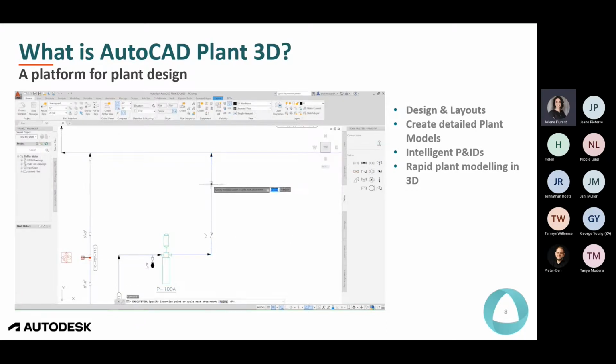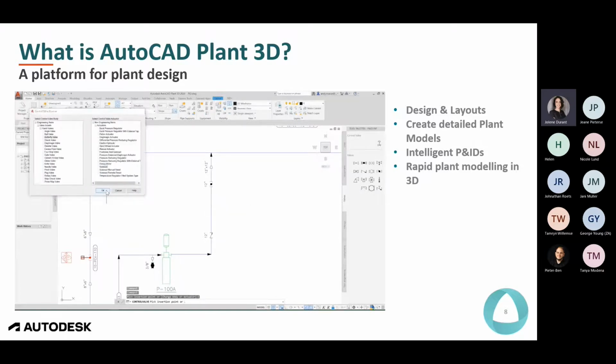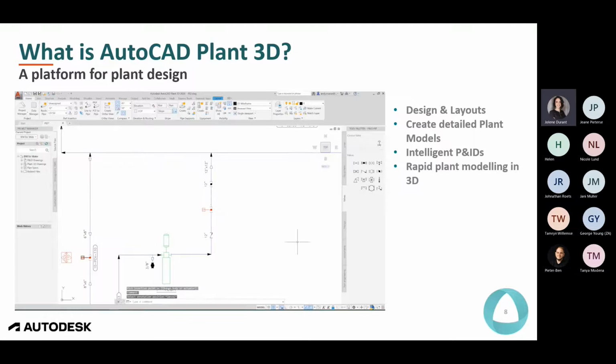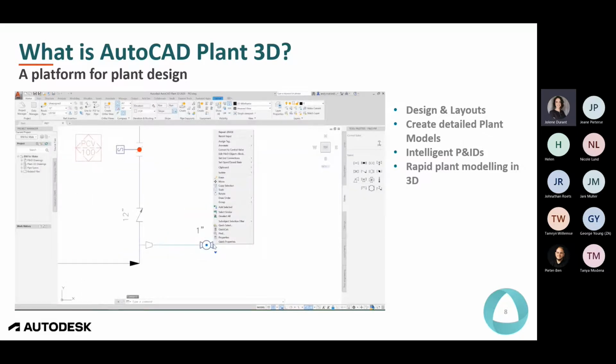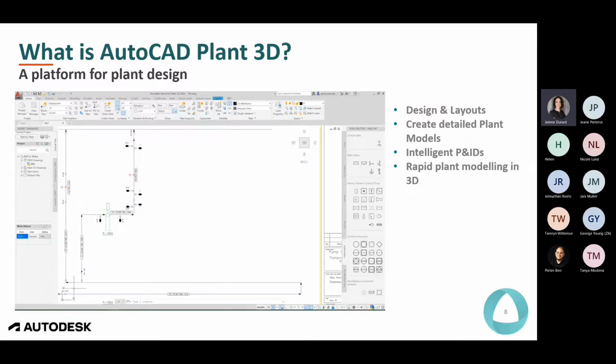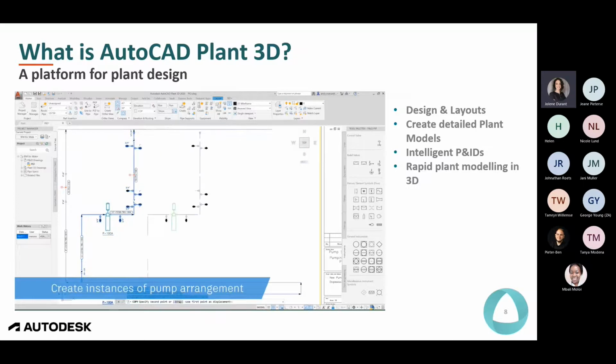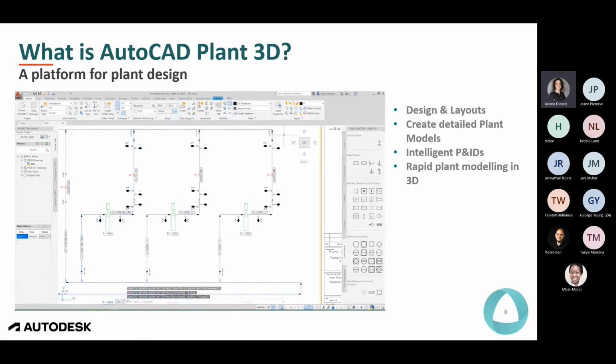When control valves are defined, the valve body and the actuator are designated to ensure the correct graphical representation, as well as correctly defining the valve in the database. Drain valves can be set to normally closed, which will automatically change the symbol representation. Once the first pump configuration is now complete, we can simply use AutoCAD functions to copy the pump configurations.